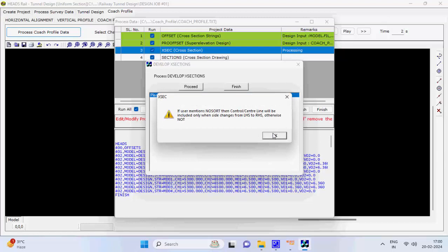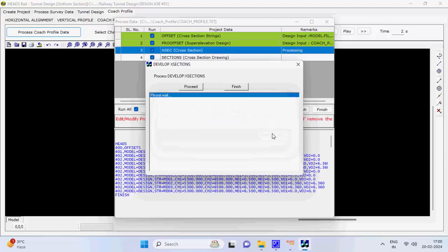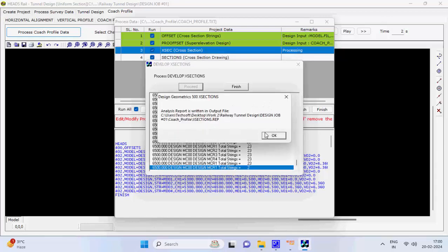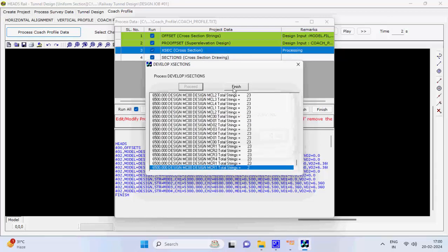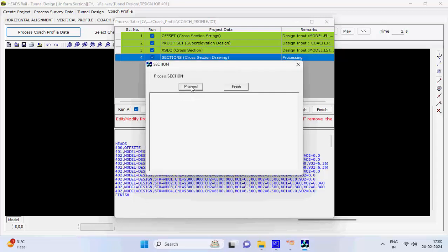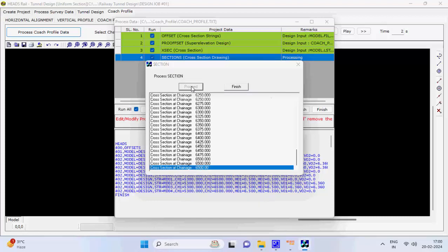Step 200. Click on the button View project data file. The project data file is displayed on the screen and is also opened in Notepad to take printouts. This is the backup file of the design data and may be processed along with the total station survey data by taking these files in a new folder. Step 201. Click on button Proceed.